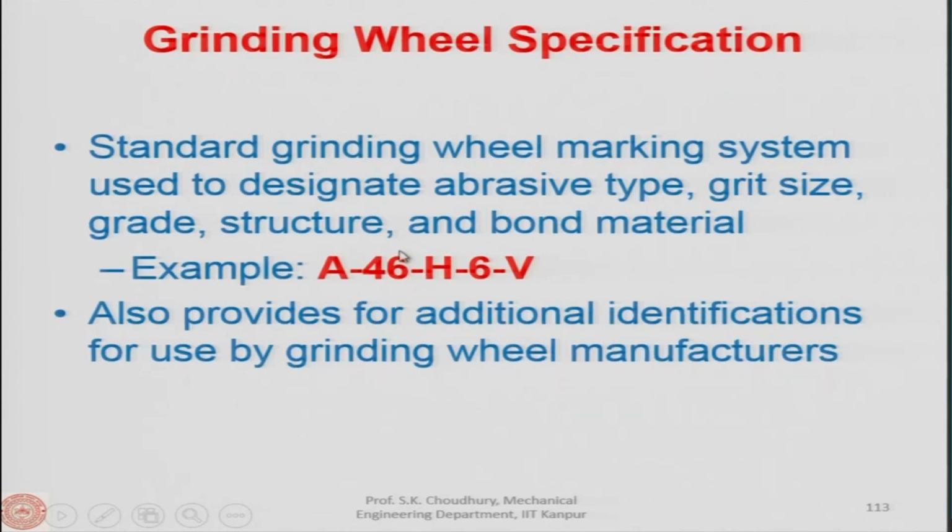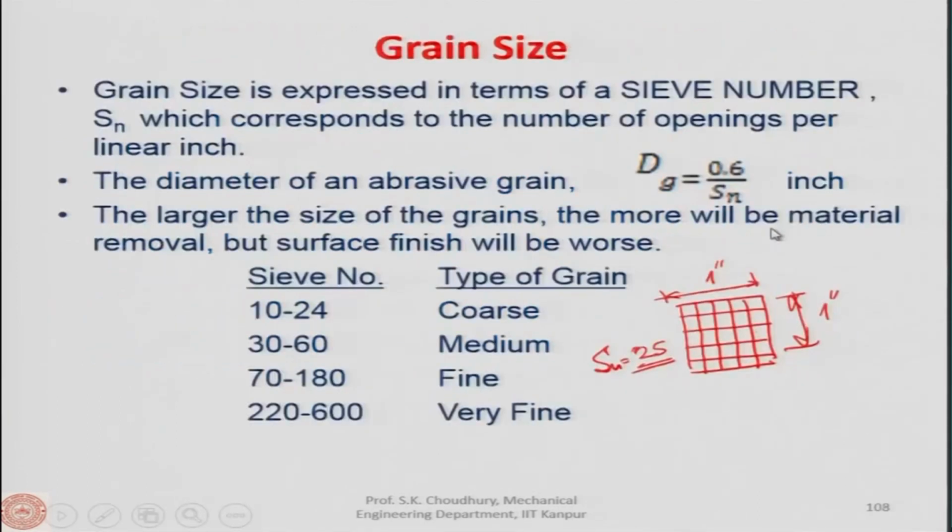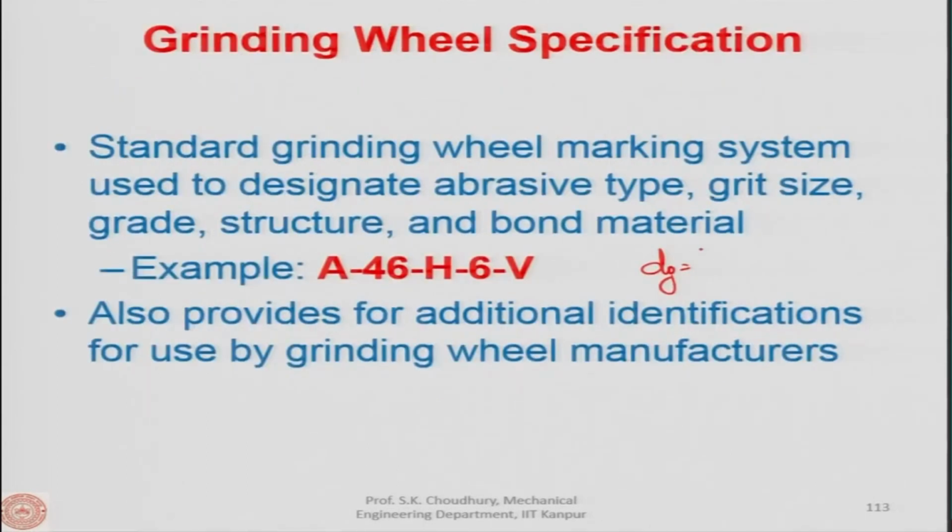The size of the abrasive grain is 46, and the diameter of the grain we can find from here: 0.6 divided by 46, in inches, which you can convert to microns.